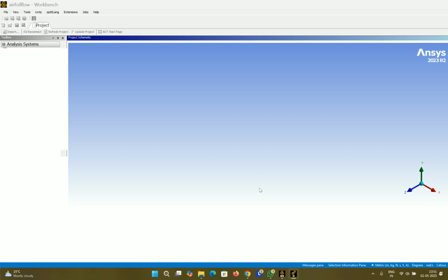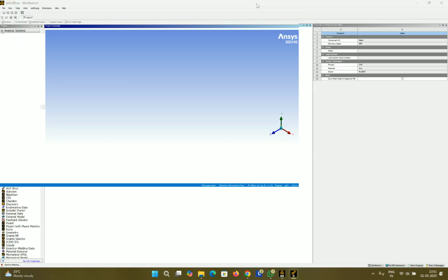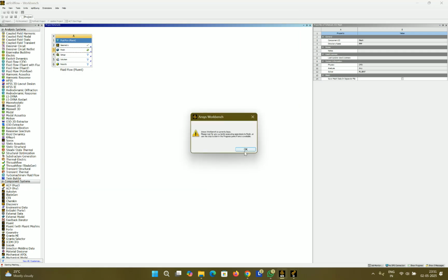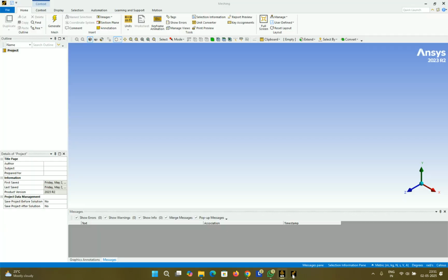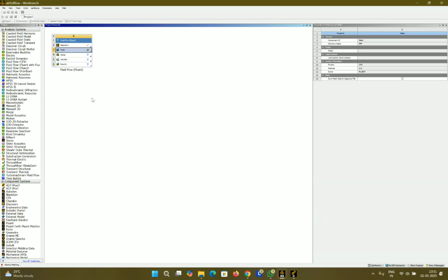It's taking quite a lot of time to open meshing. I think before we go to mesh here, I forgot a small step where I had to split the faces of the surface. So we'll go ahead into Design Modeler, complete that, and then we'll come back here. Okay, so we'll close meshing for now.